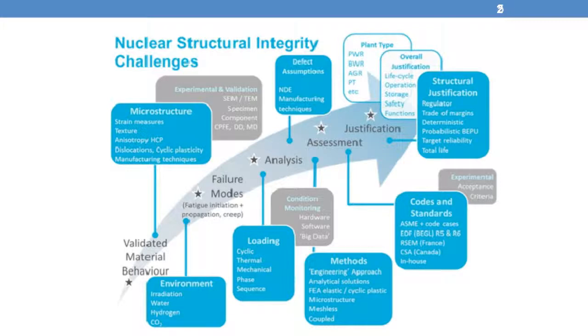of IMechE plus R6. IMechE provides assurance against plastic collapse, incremental plastic collapse and fatigue by imposing a set of stress limits based on material properties. And if these are achieved, then the design is deemed to have a margin to failure, quantified by a reserve factor or a fatigue usage factor. But importantly for today's discussion, the actual proximity to failure is not quantified.